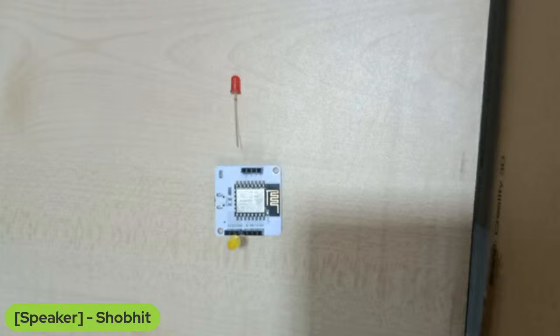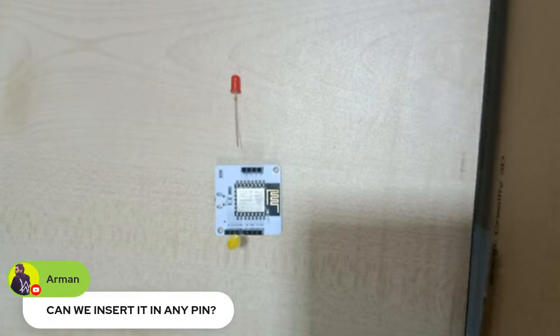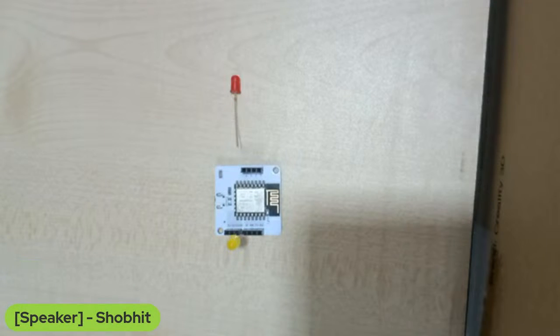I hope you have made the connections, those who have hardware. It is very simple. There are only two terminals. One will go to pin number 0, one will go to pin number 4, that is ground in this Bolt Wi-Fi module. So now comes the programming part. We should write some program to control this LED.